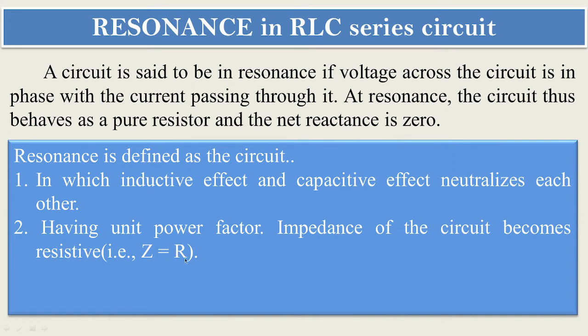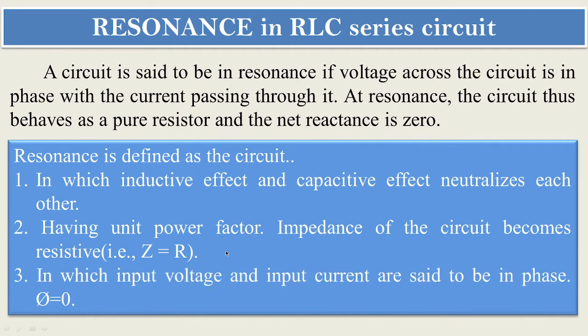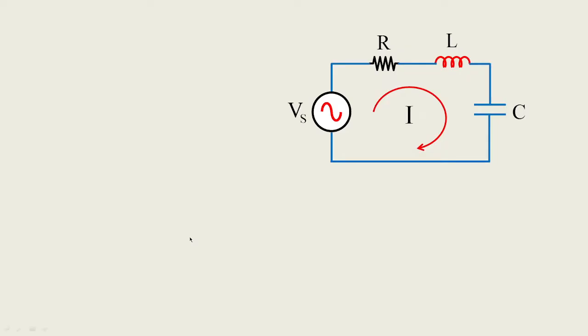So the impedance is only resistive, it doesn't have the reactance component. Also, resonance is defined as a circuit in which input voltage and input current are in phase, which we have seen from the previous definition. So all these cases match with the resonance concept. There should not be any phase delay between the current and voltage when you're talking about resonance.